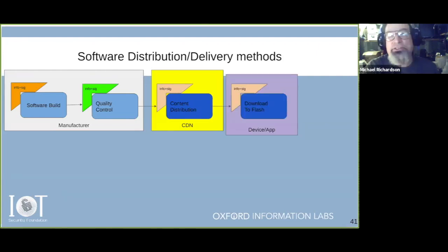The device downloads it. It puts it in flash in some way or other, whether it's single buffered or double buffered is determined. And then it verifies the signature, and it needs to also in particular verify that it's got the correct firmware for the correct model on the correct system. As an example of why that really seems like, well, that's crazy, what would be the issue? Well, it turns out for my dishwasher, which has an MCU but it's not internet enabled, there are 5 different control boards with 5 different system on chips on it.